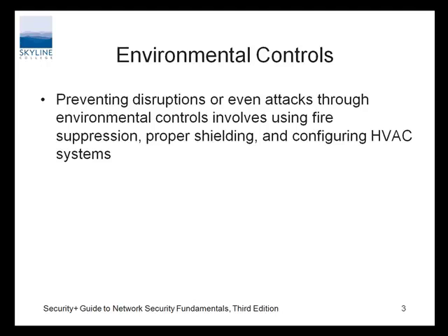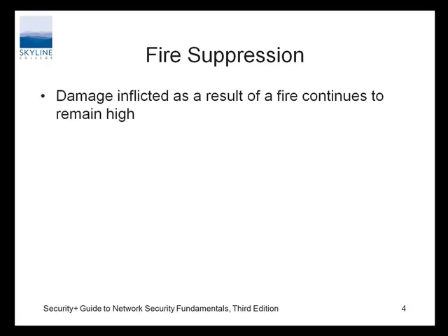There are other agents that are probably better in a flooding situation if you have occupied space. If you have unoccupied spaces, CO2 is just fine, but you've got to have an alarm so that people can get out, and you really need it so it doesn't activate in occupied spaces. It really becomes a dangerous thing.